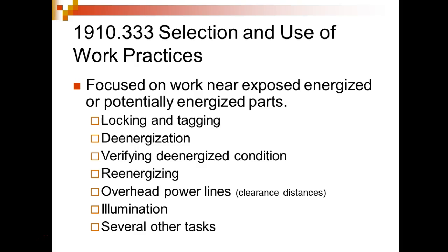Let me ask you this. You pull the disconnect or something, it's got an LED display, and you see that LED display go out. You never use that for verification. The way it's written is that you always verify with the meter. Always, which makes sense because it's a light too. Who's to say that the light didn't blow at the instant preceding?